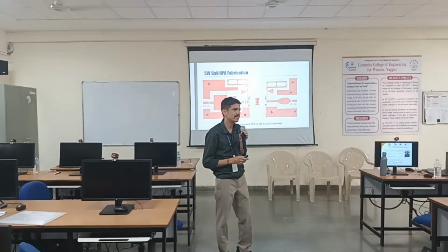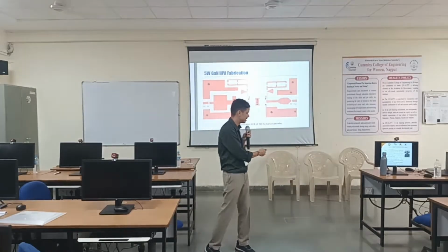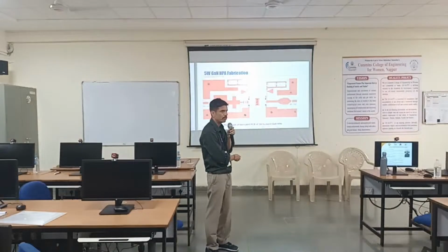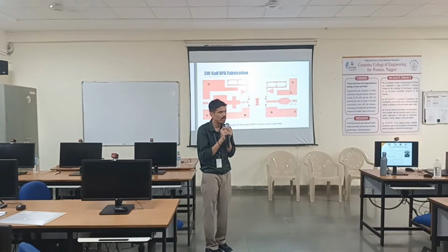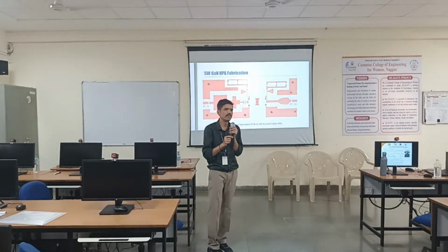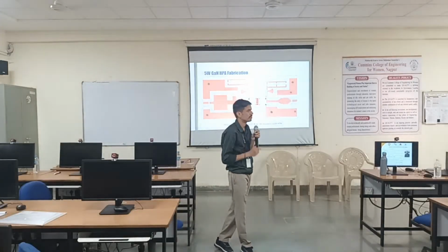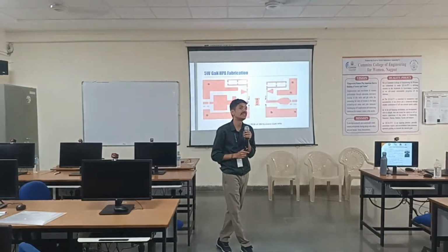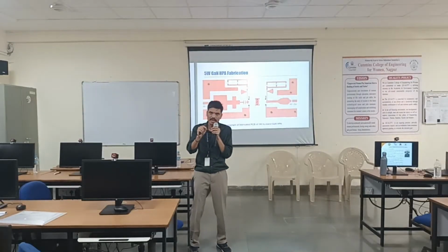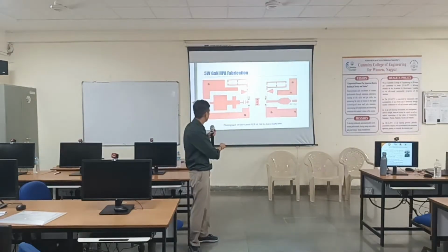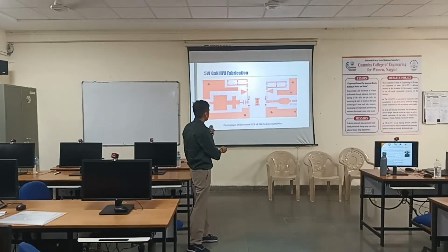What is the real challenge to get it validated? First thing is this: you should get the PCB, you should get it fabricated. It is a very complex design. No one will give you the microstrip transmission line width less than 0.5 mm. Only with laser cutting machines can you get the sharp edges and the minimum width required here. Smaller widths, 0.5 mm lines.